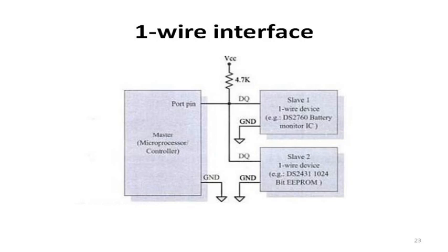These EPROM devices need a 12-volt programming pulse and are not erasable. The next leap forward was EEPROM, electrically erasable programmable ROM technology, which allows programming and erasing at 5 volts or less.